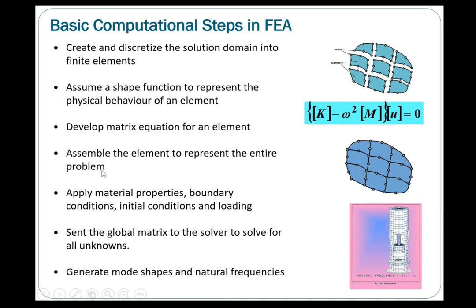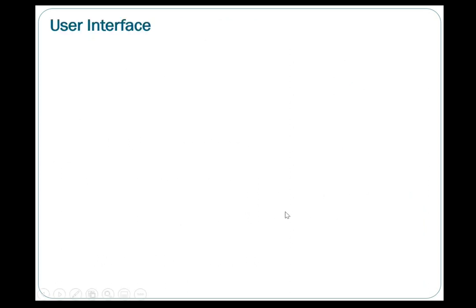Basically, it's similar to a multiple degree of freedom system. You discretize your models, your CAD model, into elements. Each element has nodes. Each node is basically your mass, your multiple degree of freedom mass, right? So if you can model in terms of n degrees of freedom, then you solve those equations, and you get your natural frequency, damping and motions.